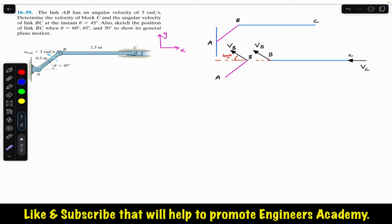Now we can write the relative velocity equation. Velocity of C is equal to velocity of B plus velocity of C relative to B. As we can see, when this link AB moves in the counterclockwise direction, block C will come towards the left and this point B will go up.